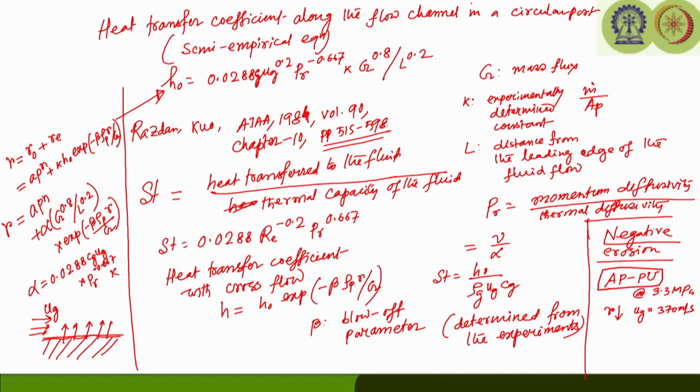Now, what was analyzed there: during close observation of the burning surface, it was revealed that the surface was partly covered with a molten layer from the binder. So part of the polyurethane binder was covering the propellant surface, which prevents further decomposition of ammonium perchlorate particles. That leads to a reduction in the heat flux coming from the gas phase to the condensed phase, due to which the burning rate was decreased.